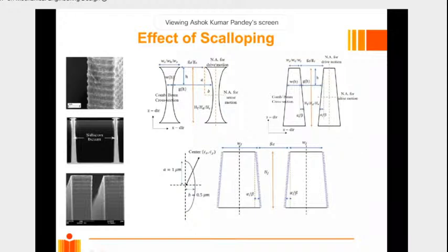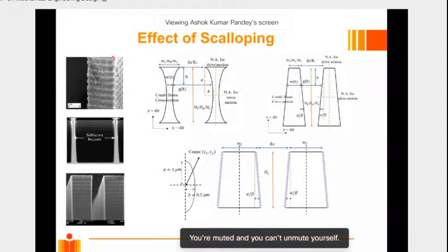Yeah. So now, what really happens during this etching when you try to etch some of these devices which are quite thick? Okay, so there is a process called DRIE. When we try to do it, we do some alternate processing, and due to that, what we can come across is some kind of scalloping along the thickness of these structures.